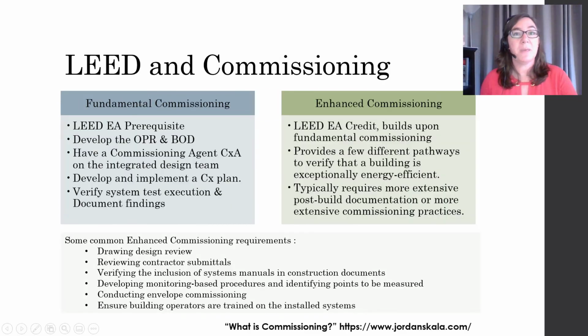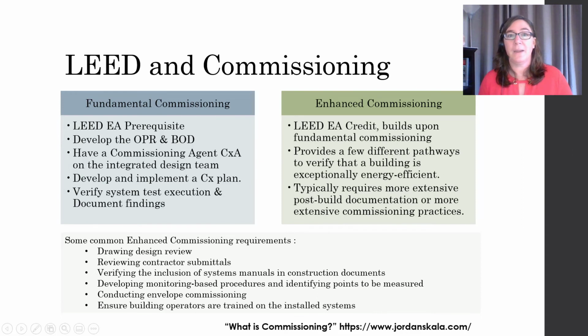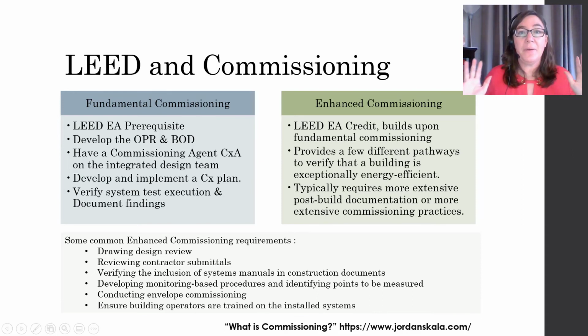So now you know what commissioning is, and two of the major terms that are involved here, the OPR and the BOD. All right, let's pull this topic back to LEED. How does LEED treat commissioning? Well, there are two different requirements for it in LEED. The first one is called fundamental commissioning. This is kind of the baseline. It's a prerequisite. All projects need to do this.